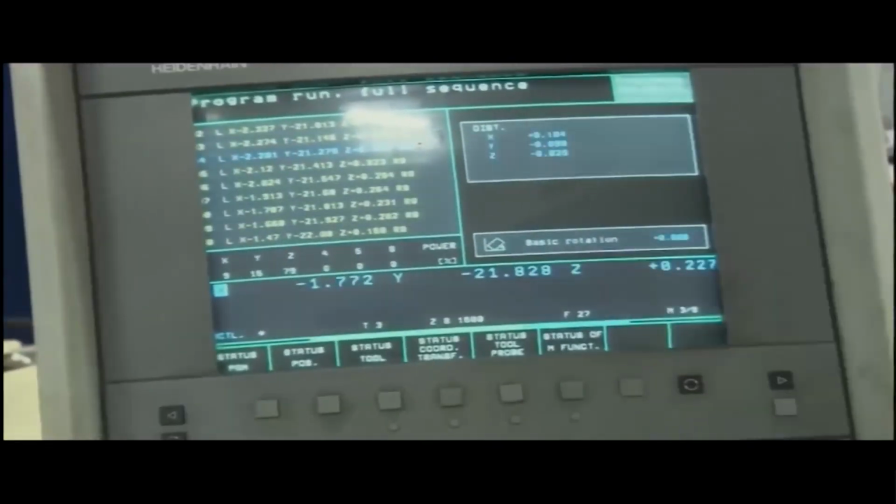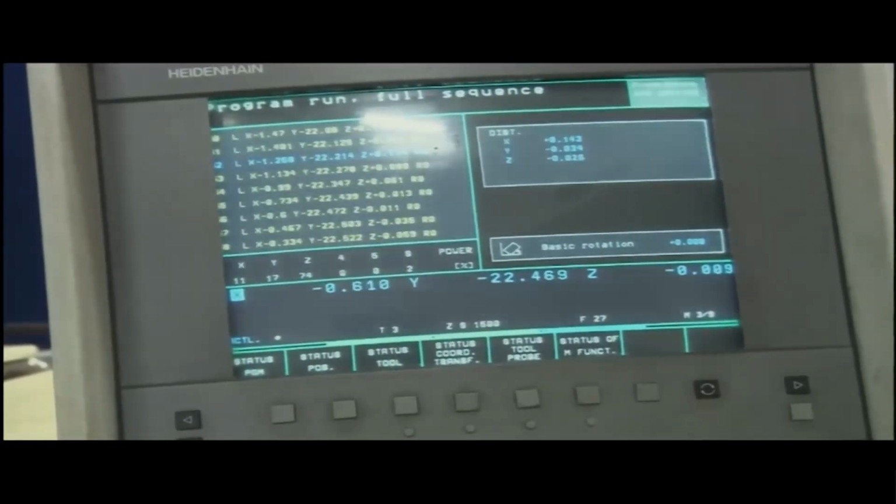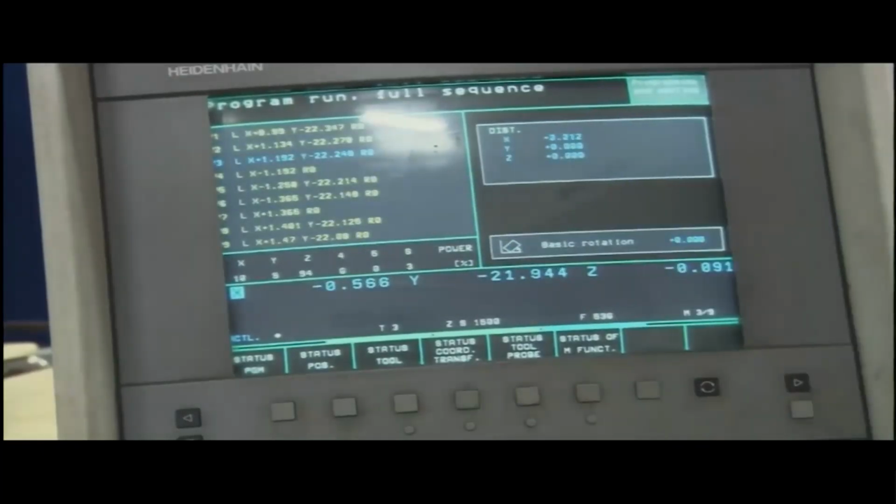Now, step by step the codes are moving, see 09, 50, the codes are moving, the movement is now going on X and Y direction. So, the tool is not moving, the Z axis is almost fixed once the plunge in has happened and cutting has started. Now, X and Y direction is all taken care by the machine table.